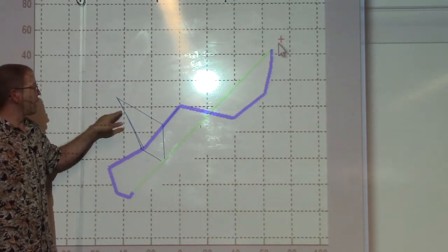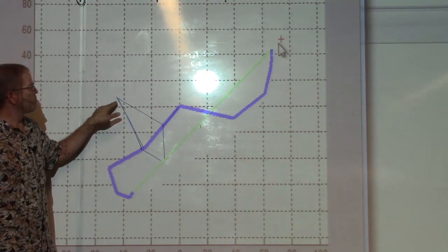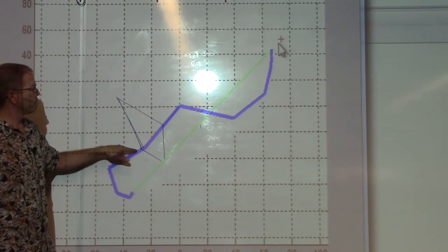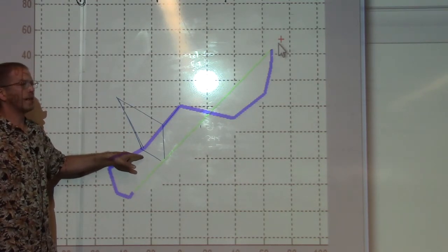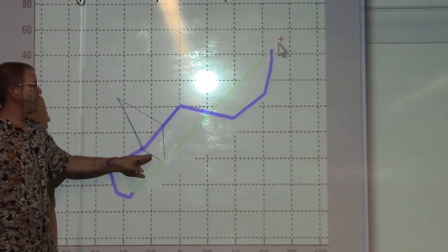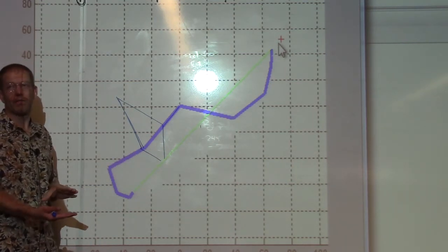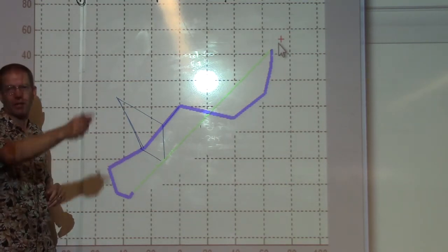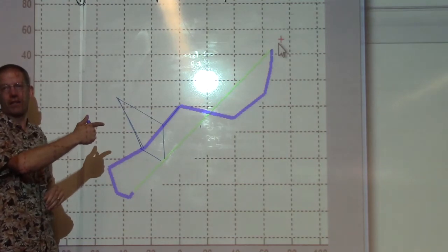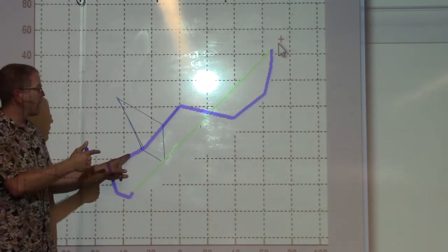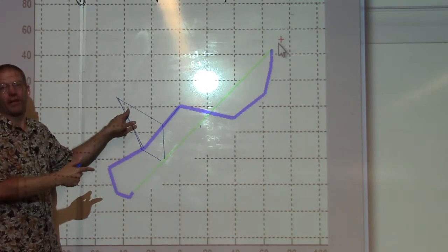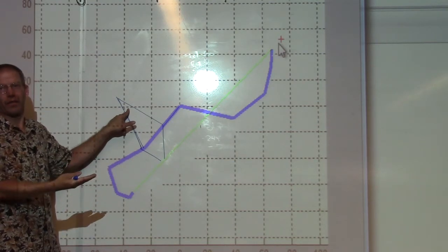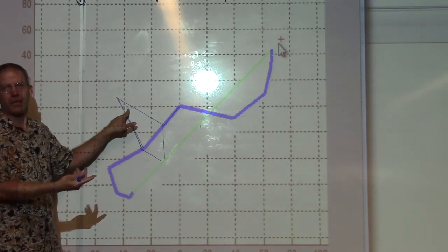But in the situation where that's just not possible, or maybe you adjust it and it doesn't produce the shortest distance, then it's going to change the rotation that it searches for the destination on. And in that case, you're going to end up with a discontinuity in those joint motions. Do you guys kind of understand what I mean there?